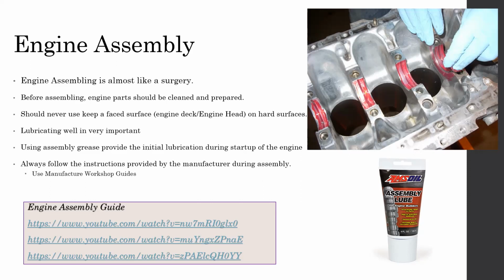And as usual, everything has to be cleaned before assembly. When assembling any engine, the engine mechanic will, before starting, make sure that he has all the components. He lines everything up in the correct way, so he can keep working on the engine. There are two reasons for that. One reason is to reduce the amount of time you spend on an open engine, because you have already cleaned it, so you're supposed to complete the assembly.